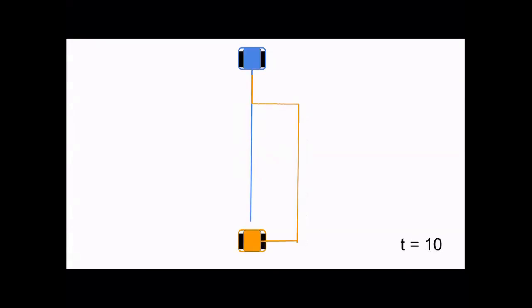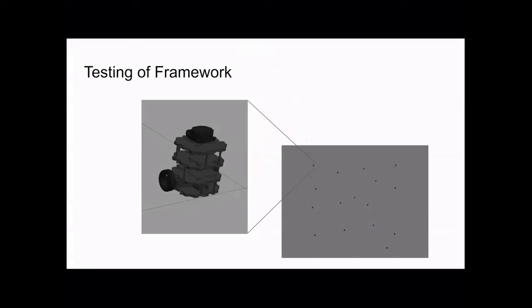When testing, we use a simulated environment with Rviz and Gazebo as well as by using ROS. By creating this environment, we were able to facilitate planning while moving, as well as having a testing environment that mirrored a real-world robotics deployment as closely as possible. We used Turtlebot 3 Burger model robots as our simulated agents. In this diagram, you can see 16 agents randomly dispersed in the simulated environment.